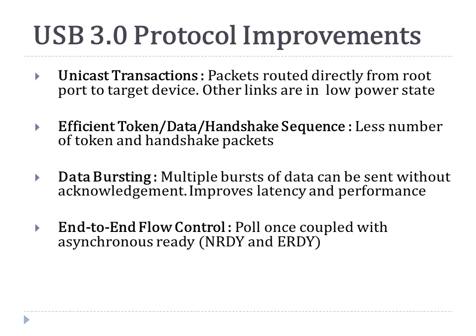And as we mentioned, USB 2.0 was a polled bus, where the host polls each device at a regular interval. But USB 3 polls only once, and when the device is ready, it sends a synchronous ready signal and the data transfer continues. But in USB 2, if the device is not ready, the host will poll again to see if the device is ready. This is made possible because of the full duplex lines in USB 3, which are not available in USB 2, so it has to do regular polling.